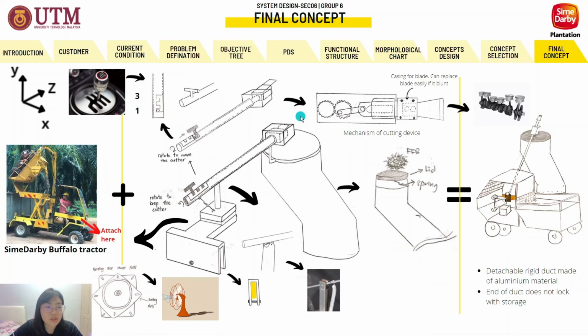So after the front is cut, the front might fall onto the collecting duct lid. However, the big surface of the front will not cause the lid to open and the worker can just shake off the front by adjusting the device angle. Oppositely, when the FFB is cut, the FFB will exert a point force onto the lid and cause the lid to open. The lid will return back to the original position due to the compression force of this spring.